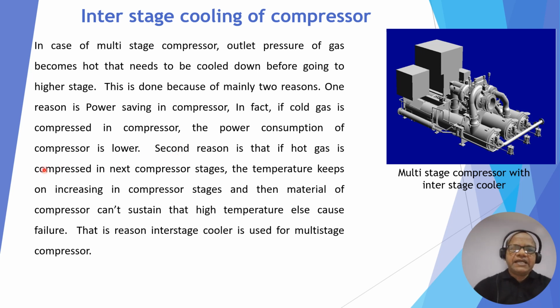The second reason is that if the hot gas is compressed in the next stage, then the temperature keeps on increasing. Let's say if the inlet of the first stage is 30 degrees and the outlet is 100 degrees, then if that 100 degree gas is compressed again in another stage, it becomes, let's say, 200 degrees, and so it keeps on increasing.